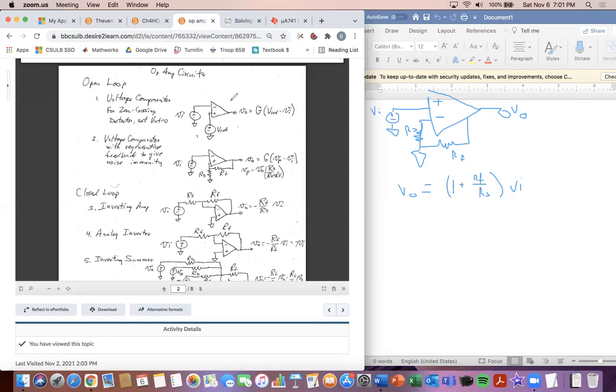Okay, what happens is if you guys see here, remember how the feedback resistor I always told you guys goes to the negative terminal here, and then we have RS? Well, what happens if we want it to be an open loop? Remember how no current flows through an open circuit? In an open circuit, you can think of it as infinite resistance since no current goes through. This value of RF is so great in comparison to RS because it's just an open loop here. There's no resistor actually here, so this gain is infinite in an open loop.